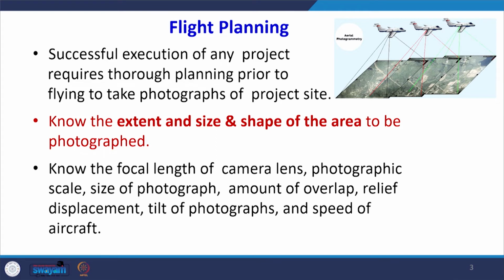Now, why is it required? So that we know the extent, size and shape of the area. This is very important before we take up the project. How much is the extent of my area, what is the size, what is the shape, what are the different terrain features, what is the elevation difference in my area. All this we will come to know with the help of these photographs.